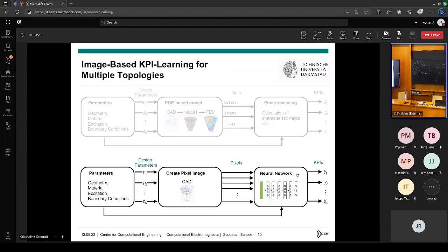What we also tried in this work, that was the very first idea, if you have very complicated CAD models, and it may be the issue that these template-based CAD models are even differently parameterized, right? Even if it looks the same, the parameters may be different because a different designer has created those parameters. And then the issue is, okay, how to use that in learning? The first idea was that we create pixel images, which in 2D is supposed to work nicely. Well, in 3D, maybe questionable, but in 2D, we expect it to be nice. But this turned out to be not very successful. You need very fine resolution, which really increases the parameter space you have by a lot. The only way to make that somehow work was in the end to feed those parameters and the images. Then we could get proper prediction quality. So this approach, at some point, we dropped essentially.